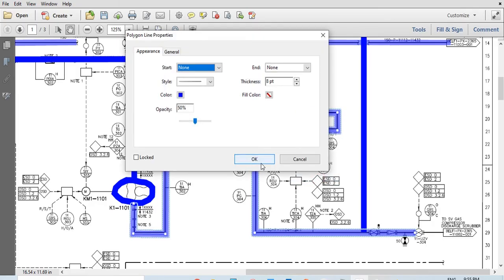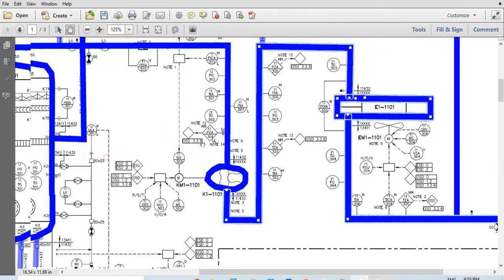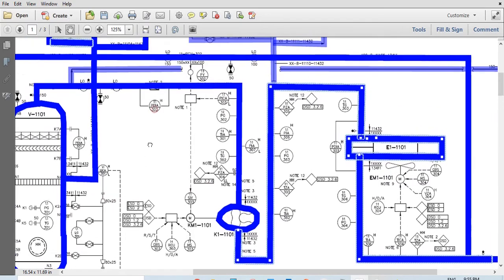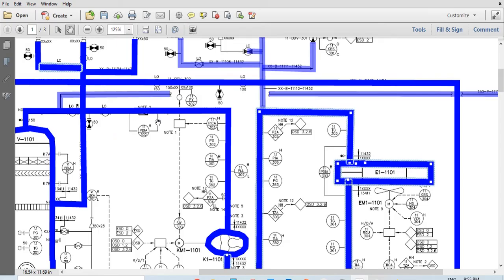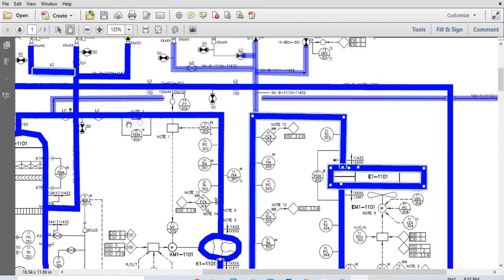You know, we still have a lot of instrumentation to count, right? So we counted the instrumentation up to here. Going from that, we have instruments here. Here, this is a PDIA, checking the difference in pressure between here and here, just in case this outlet gets blocked.